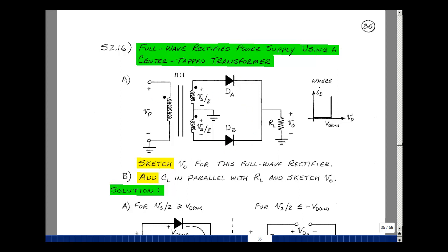In order to do that, you need a center tap transformer. Now, having 2 diodes instead of 4, we'll be able to cut the cost of the diodes in half. Unfortunately, a center tap transformer is usually more expensive than a single output transformer. When the diodes were vacuum tubes, cutting the number of diodes in half was significant in terms of cost savings. Now, the cost of the transformer outweighs the savings of the diodes.